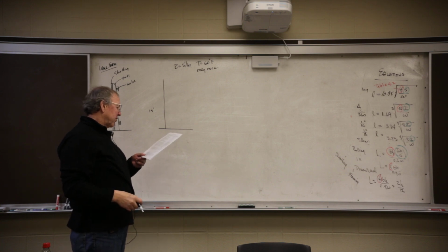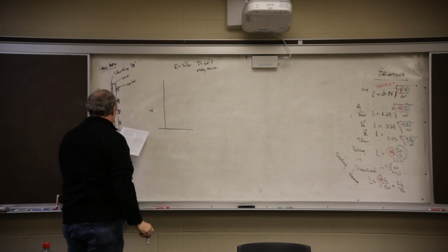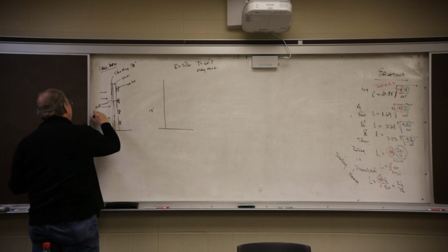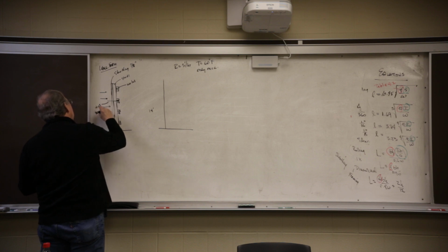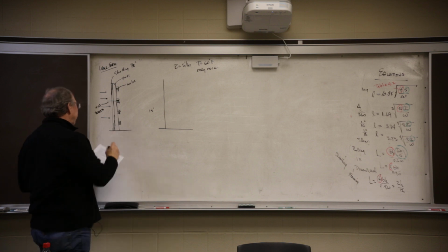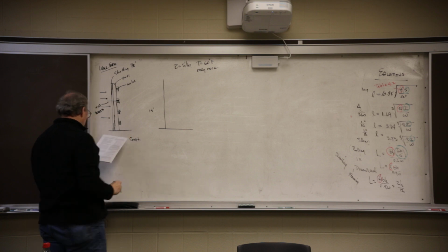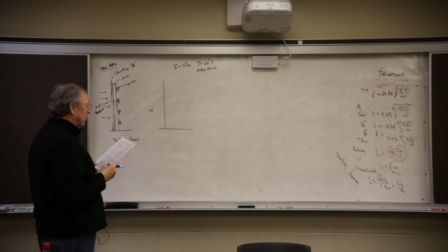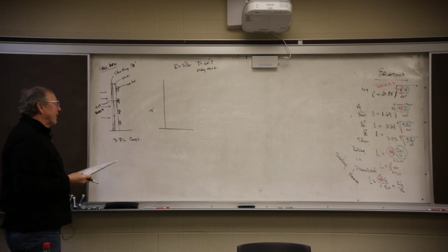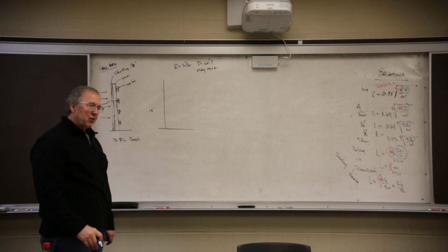We're going to use 7/8 inch plywood. So I've got right here 7/8 inch thick plywood, 4x8 sheets, 3,000 pound ties. Framing lumber: construction grade Doug fir-larch, construction grade, and purchased as required. Okay, first thing we need to figure out is the loading that is going to happen on the wall.